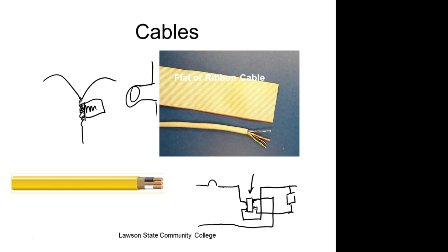and every other thing on the circuit. But what a ground fault does, it looks for an unbalance between your hot and your neutral, because all the current out is supposed to be the what? The current coming back. So it's got a little current transformer on there. And as long as those things are equal, the current transformer don't do anything. And if they become unequal, it means that current is going somewhere else, and it's usually going through you or somebody or some way, and it'll kick your ground fault. And sometimes it does. If you got plugs going outside, sometimes the cord gets wet. It'll trip your ground fault because it'll capacity couple into your ground.